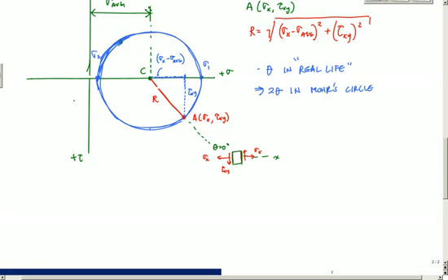And so here, if I want to look at the principal stresses, if I want to get to sigma 1, I've got to go this angle right here, alpha. In order to calculate that angle alpha, tangent of alpha is the opposite over the adjacent, tau xy over sigma x minus sigma average. And then we would do the inverse tangent and calculate alpha. This alpha is equal to 2 theta, and if we want to get theta, it would be alpha divided by 2.